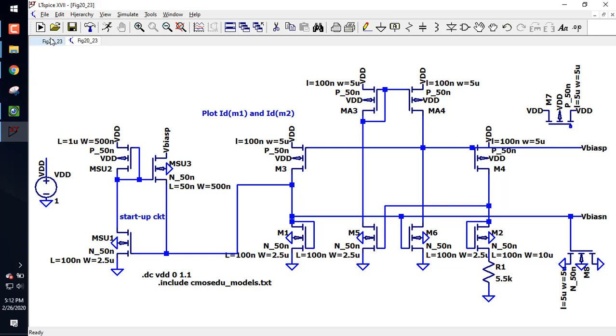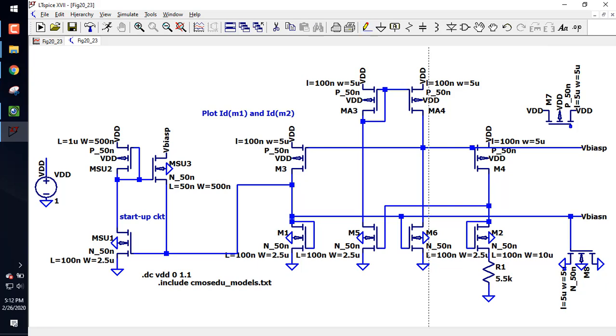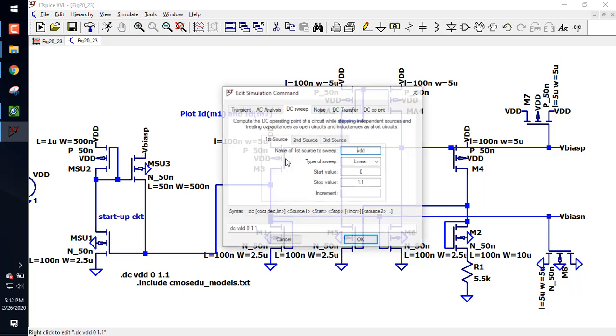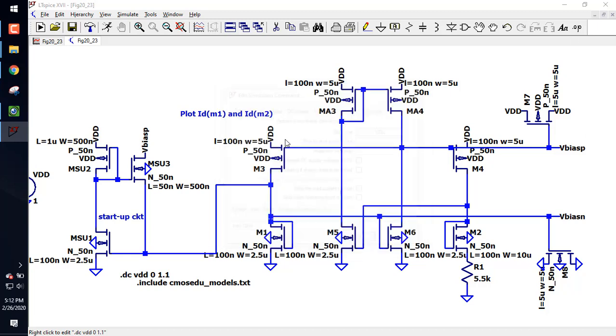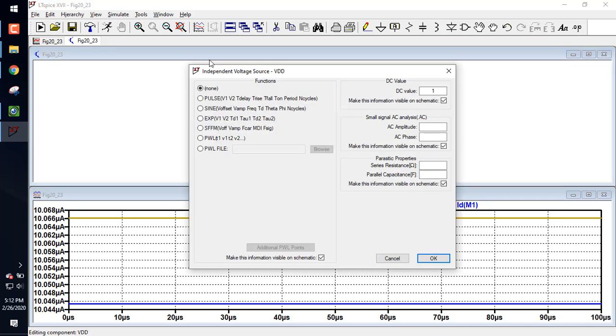Oh, wait a sec. Can I see stability in a DC sweep? Nope. So let's go do this again where I do a transient. Let's go over here, and I'm going to just do a dot tran. And let's do 100 microseconds. Let's see what happens. And I hit run, and I look at the two currents. And actually, you know what, let's be fancy and let's pulse this from 0 to...